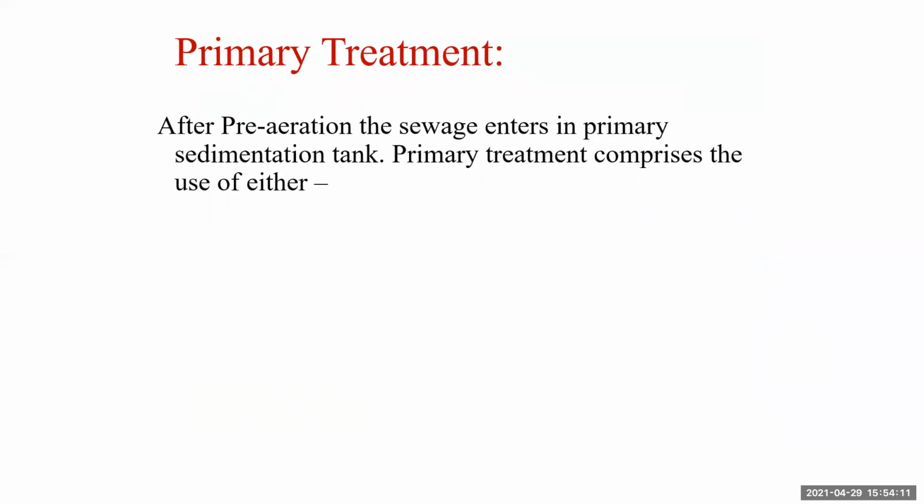During preliminary treatment, the third process carried out after screening and grit removal is pre-aeration. Pre-aeration enriches the sewage with oxygen. Okay, so after pre-aeration, sewage enters the primary sedimentation tank.